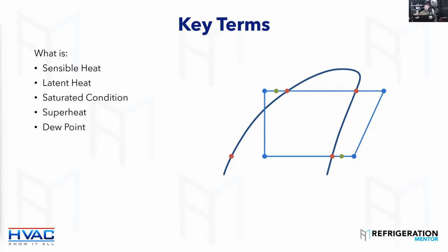I think dew point and bubble point are confusing to a lot of people. I think that maybe the term glide might help. Yeah, we'll get to that. That's in here. Okay, perfect. So the dew point is important to understand. Robertson, go ahead. Well, anything below that dew point temperature, you're going to start condensing, creating condensation.